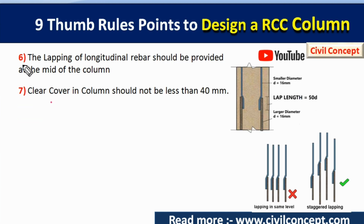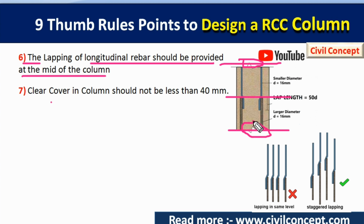Now point number 6 is the lapping of the longitudinal rebar should be provided at the mid of the column. So this is a very important term. If this is our column, the lapping should be provided at the mid of this column. We should not provide it at the upper end or the lower end. It will be dangerous because the maximum moment in the column is applied at the end of the column.